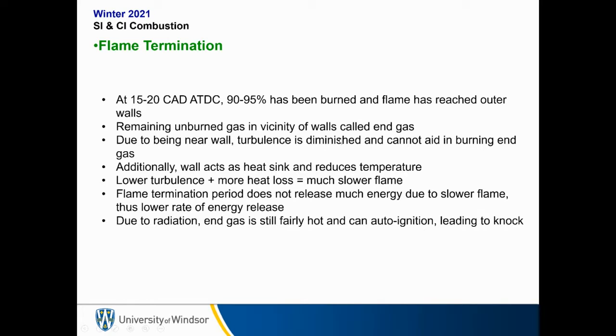Due to being near the wall, we don't have a lot of turbulence. Remember, we have a no-slip condition at the wall, and this cannot aid in burning the end gas. Additionally, the wall acts as a heat sink and reduces temperature. So lower temperature and lower turbulence equals a much slower flame. The flame termination doesn't release much energy due to the slower flame, thus a lower rate of energy release.